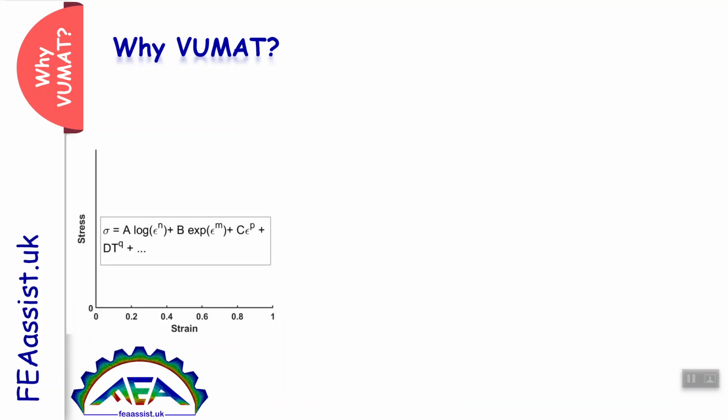But what if you have a new equation for a new material, a new constitutive equation, and the equation is not included in the Abaqus to enter the parameters and constants? Then you will need a place to write your equations and force the Abaqus to solve the problem based on your equations. This place is VUMAT Subroutine.